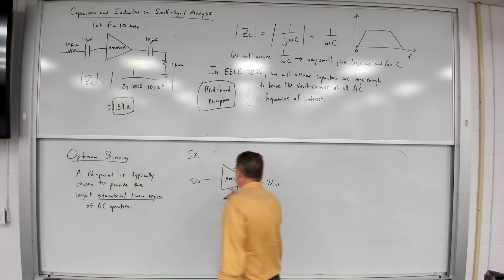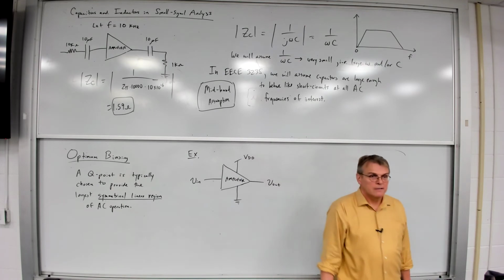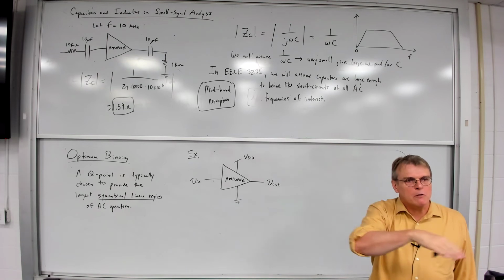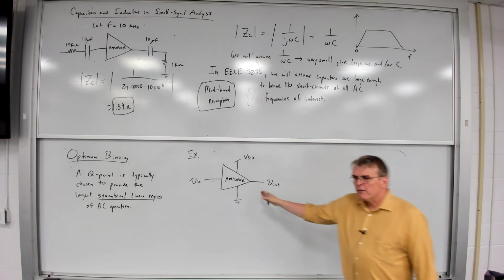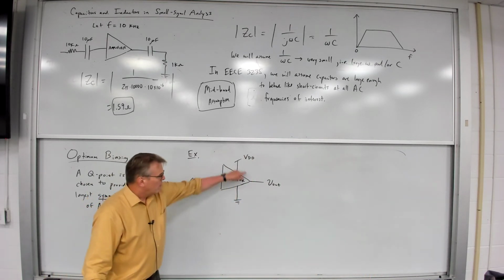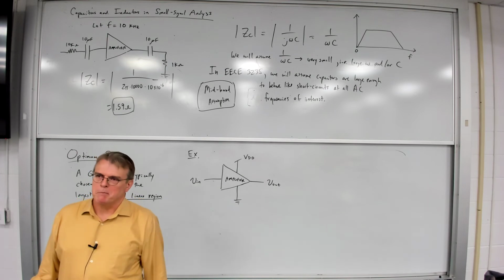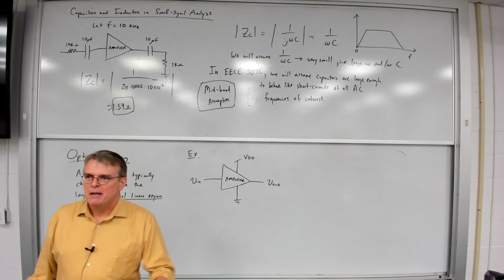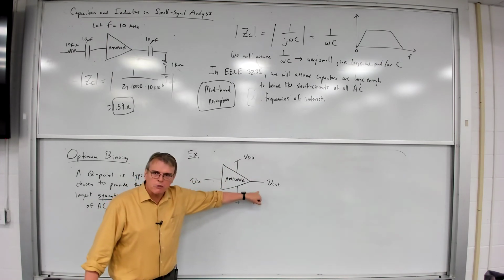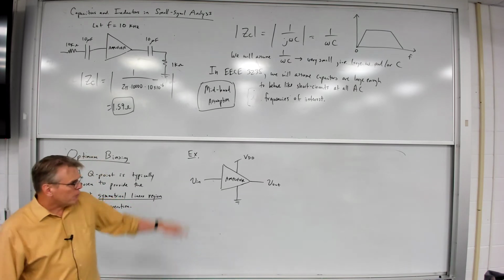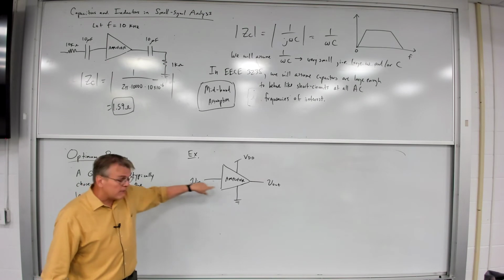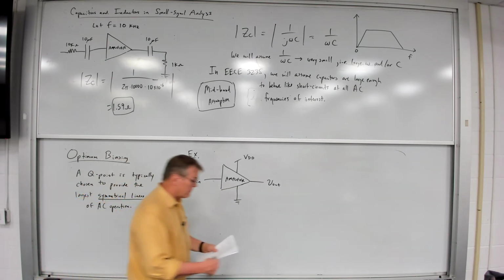Now, this amplifier, what you're going to find is, if you were to actually do the large signal model of this amplifier, you'd find out that it's not a perfectly linear circuit. What do we know about amplifiers? Well, think back on op amps. Op amps saturate. Op amps cannot go past the power supply voltage or the ground in terms of the range of outputs. So if you were to actually go through and do a large signal graph of the response with DC voltages and DC outputs, you'd probably see something like this.